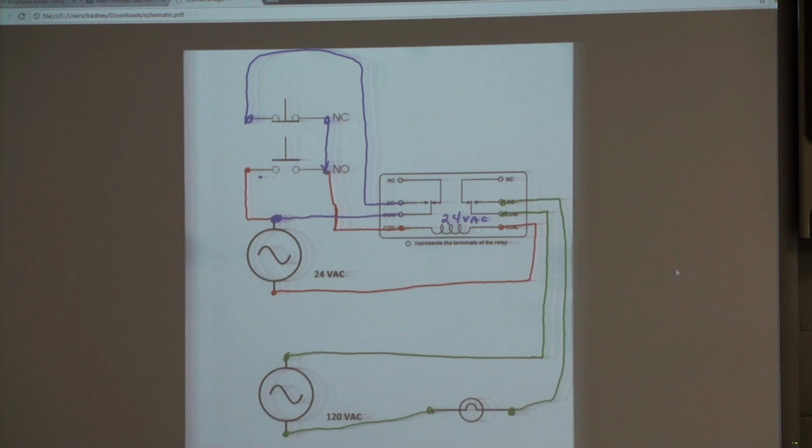That is the third part of that circuit that tries to throw us when we start talking about latches and latching a circuit. But that's all it is to it. It's a bypass for the switch once the switch is engaged. And that's the beauty. It doesn't become high until the coil is energized. Once the coil is energized, it's high until you press the normally closed switch. Then it opens right up, coil drops, no more voltage. So, kind of a neat circuit, and I think I'm seeing some folks really start to get it now.